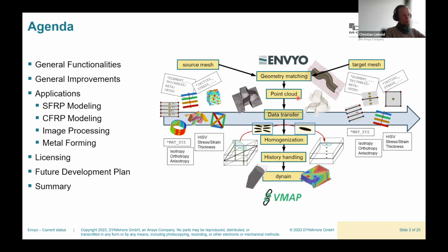So we try to consider where the information has been stored. If you have an LS-DYNA input mesh, you usually have temperatures stored on nodes, thicknesses as well. You do have orientation on elements or on integration points, depending on which kind of modeling approach you consider, for example, metal forming with specific rolling directions, or if you have a composite material with laminate stacking sequences, then you have orientation information on the integration points at different positions, or even just on the element center. We generate those point clouds to perform the data transfer.